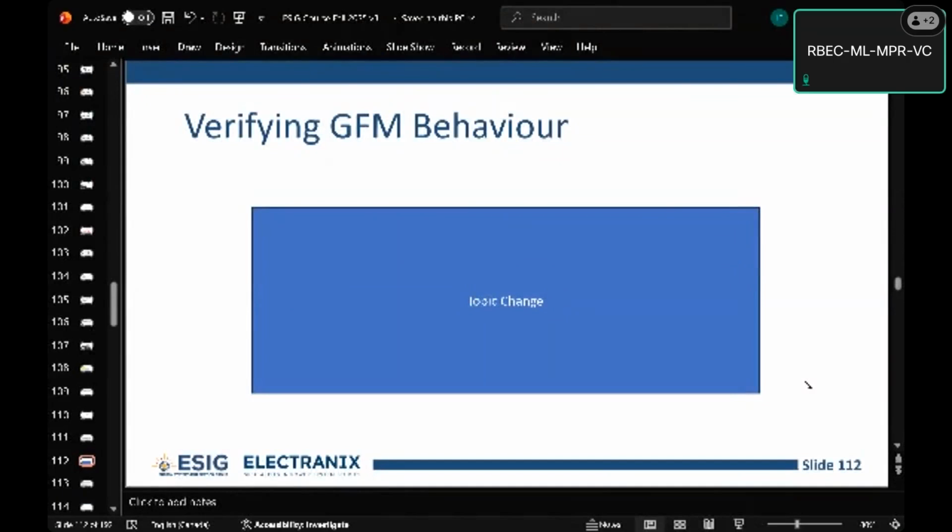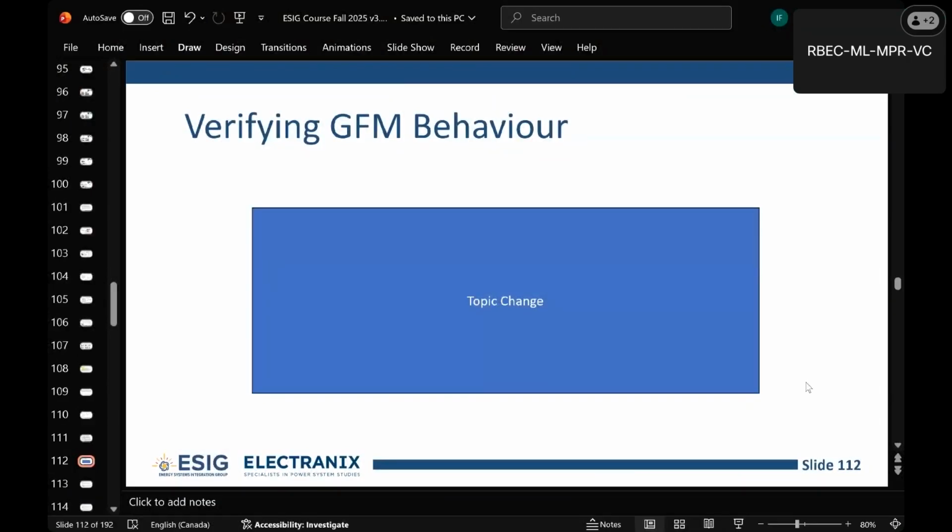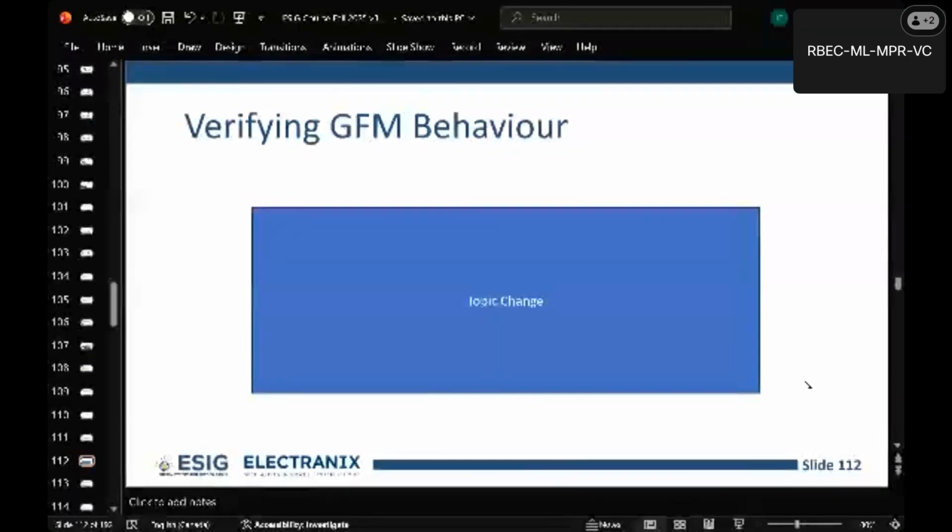Next. Have you done any full-time field study for solar plus storage systems? Yeah. To see the interaction between GFL and GFM? Yeah. Is there any interaction between doing both right? I mean, you put a fault on and they both have a ride-through profile. The grid forming will stabilize the system, so the fault ride-through for the grid following will be better.